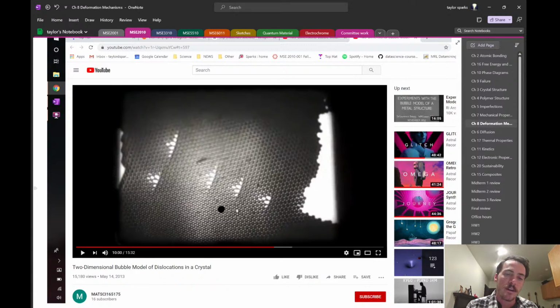If that's there, then this dislocation will want to come and park right next to it because you've got this compressive region from the extra half row of atoms, then you have this tensile region, and that's being offset by the region of compression from that dislocation around it. So it does what we call dislocation pinning. It pins it in place. So that's going to change its mechanical properties. That's one example of how an alloy and a pure metal will change their mechanical properties.